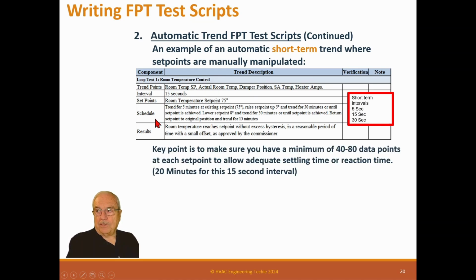A key point is to make sure you have a minimum of 40 to 80 data points, so each of the set points will allow adequate settling time or reaction time. 20 minutes for a 15-second interval. So that should be fine.